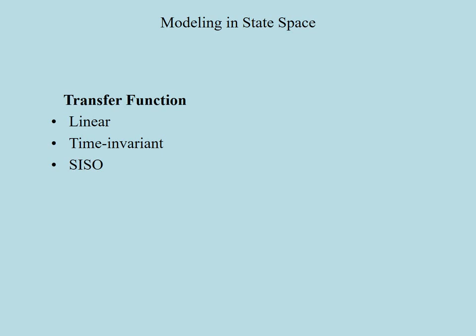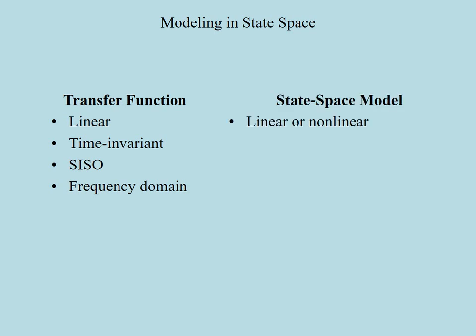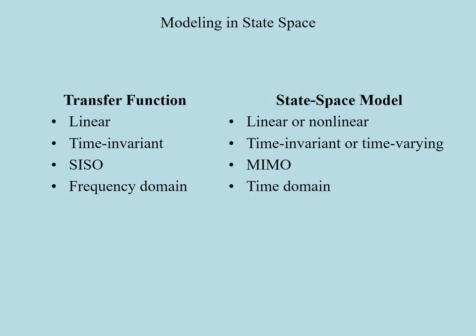They are based on Laplace transforms, therefore they constitute a frequency domain approach to modeling dynamic systems. On the other hand, state space models can be used to model linear or nonlinear, time invariant or time varying, multi-input, multi-output, as well as single input, single output systems. Besides, they are time domain entities. In other words, they are differential equations in a special format.